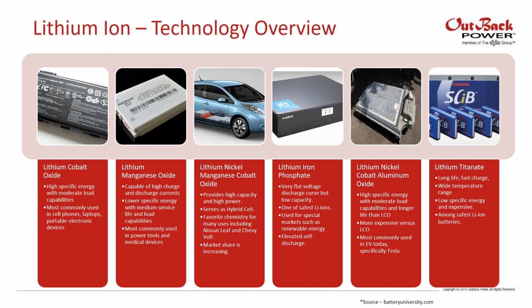They also do run the possibility of having a thermal runaway event and causing cell failure. They all run that possibility, although the safest chemistry is iron phosphate, where that potential is very small compared to the others. And specific to lithium cobalt oxide, cobalt is really hard to find in nature. The abundance is pretty small, so the raw materials are hard to come by, and that will probably increase the cost, and then they'll run out sooner.